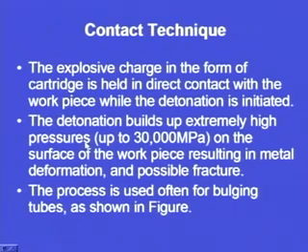There also a pressure pulse was created; here also extremely high pressure, to the tune of 30,000 megapascal, is created. When we detonate, the pressure rises on the surface of the workpiece, resulting in metal deformation and possible fracture. As there is direct contact, a number of parameters in this process have to be controlled.